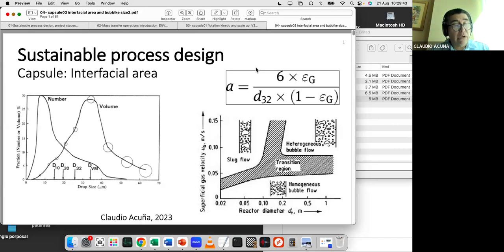For example, I want to illustrate something. You can have milk in a pot, heated, and it will take 2 hours to convert this milk into powder. You know what I mean? You put heat, you evaporate the water, you concentrate it. It will take hours. But if you take the same milk and generate small droplets, 20 micron droplets, and put them in hot air, it will take 5 seconds. You know what I'm trying to say?